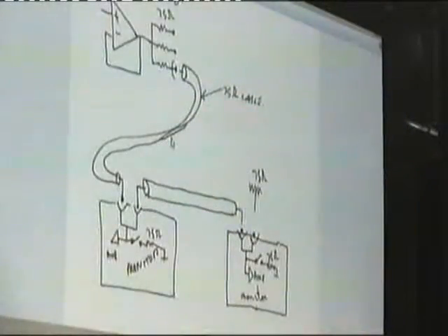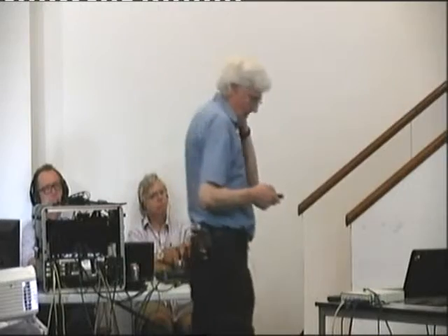And this reflection that I mentioned, although there it's exactly cancelling the subcarrier, if that was a real picture with fine detail on it, you would see that there were reflections. If there was a transition, perhaps some railings, they would have a ghost following them. So termination is a very boring subject, but it's quite important to get it right.